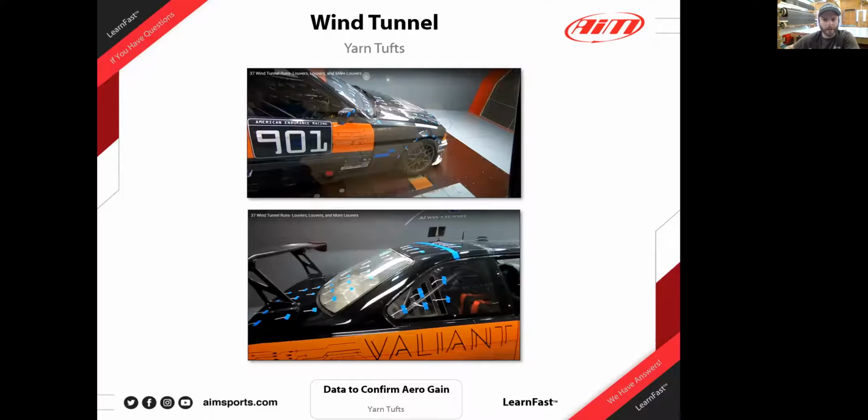But yeah, again, wool tufts can tell you a lot just by looking at them, where air is going. In the top picture, you can see the ones at the base of the hood, but not on the windshield, are going almost down and in a little bit. Yeah, because I don't think the cowl panel was sealed under this. So they almost want to wrap down and in, because under the hood is lower pressure than right at the base of the windshield there.